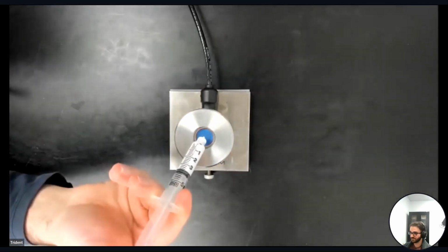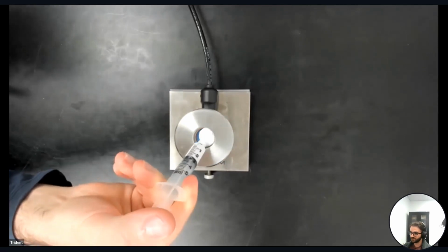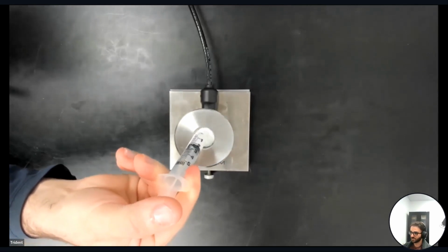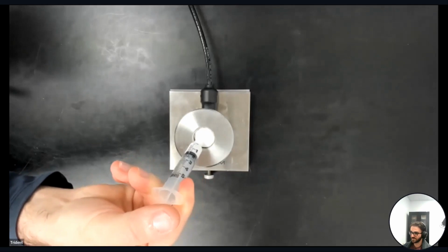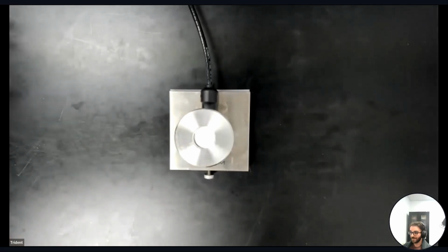So we see the MTPS sensor laid out in front. That's a liquids and powders cell that we're placing over top of the sensor. This, of course, can be used to contain these non-solids. The thermal grease you can see there is being ejected from the syringe, filling up, making sure we're covering the active area of the sensor. Just as a note, only needed about 2 milliliters of total volume there. And with that, we're essentially ready to start our measurement.